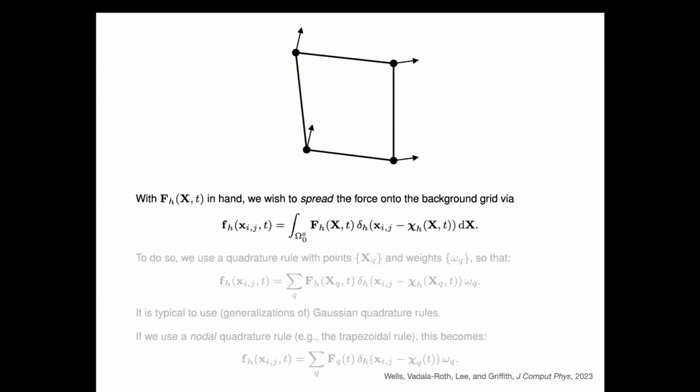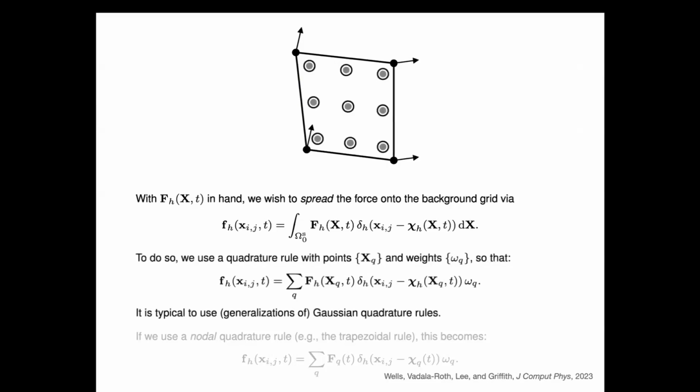The finite element mechanics model tells us what the nodal forces are. Because we are describing the solid structural force as a field that is determined by interpolating these nodal forces throughout the solid body, we can evaluate the forces anywhere. In particular, you could evaluate them at Gauss rules that you're using to discretize these kinds of integrals.